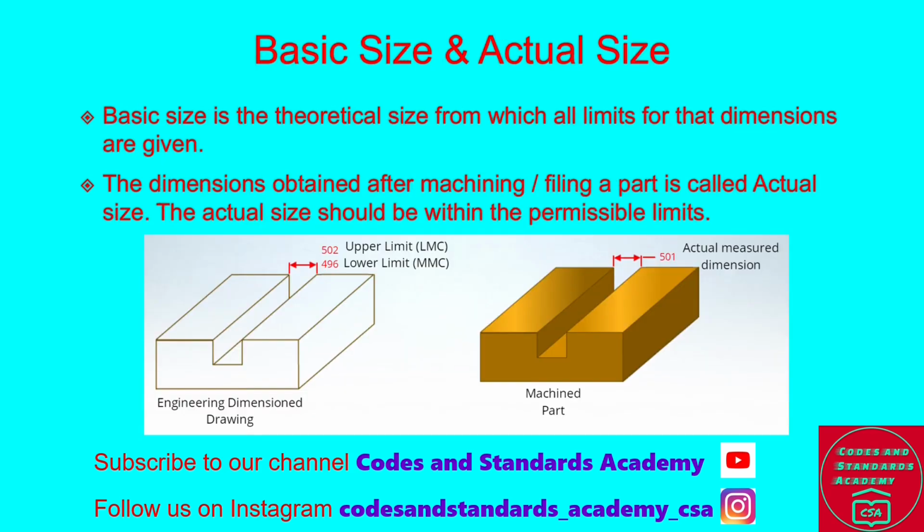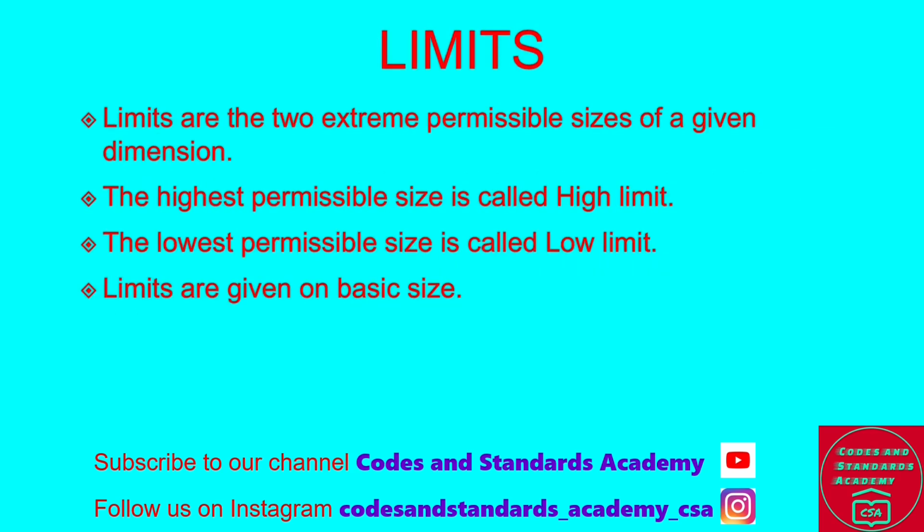Basic size. Basic size is the theoretical size from which all limits for the dimensions are given. The dimensions obtained after machining or filing a part is called actual size. The actual size should be within the permissible limits.